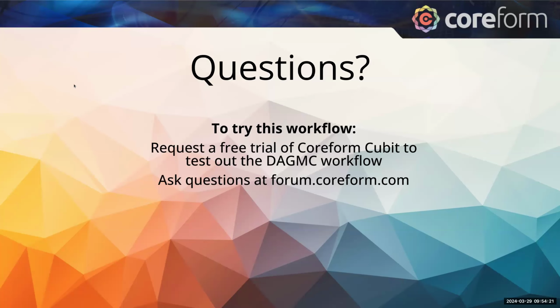One benefit would be that if you're planning on running this not just with OpenMC, but also with some of the other codes that DAGMC supports, like MCNP or Shift or Geant4, then you would want those boundary conditions to apply to all of the codes and therefore be in the Cubit model itself and the resulting H5M. So I think that is where it would really be of benefit.